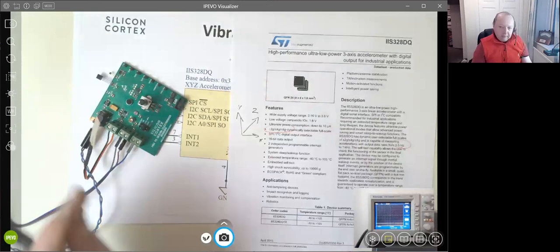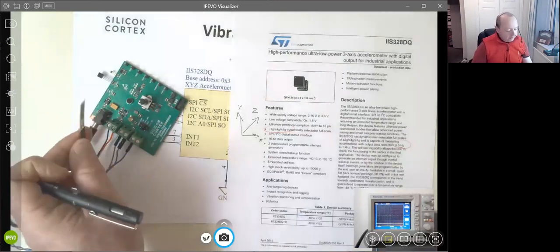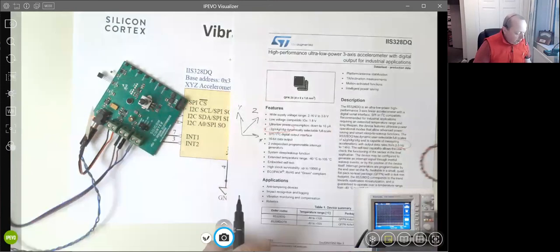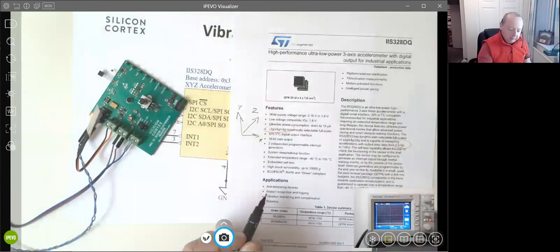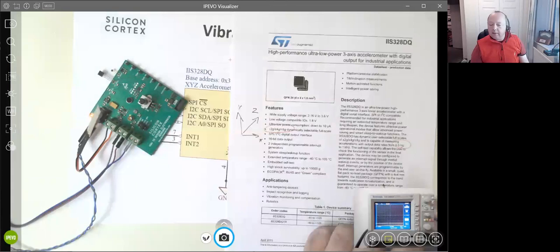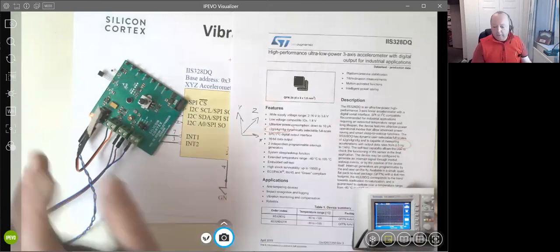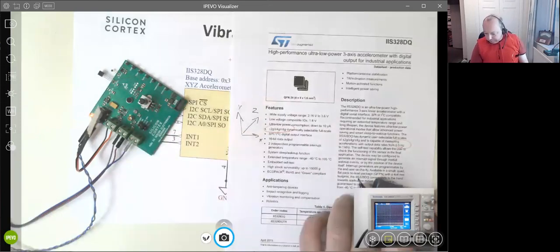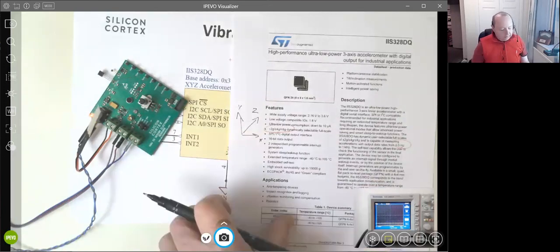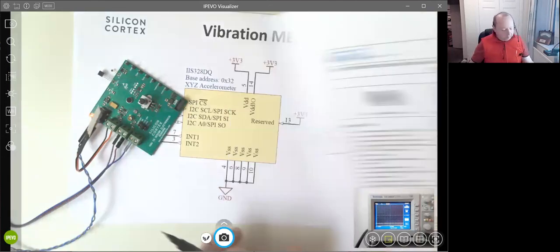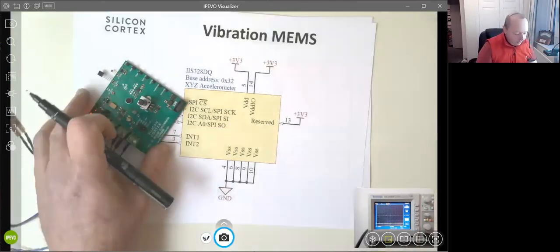So these are at least twice the price, and you've probably got just as much supporting electronics as you have with an accelerometer. So I'm not entirely sure how much saving there is today in going with a piezo. Frequency response would probably be what would make you decide one over the other. Right, so there's accelerometers for you. Most popular one by a long way.